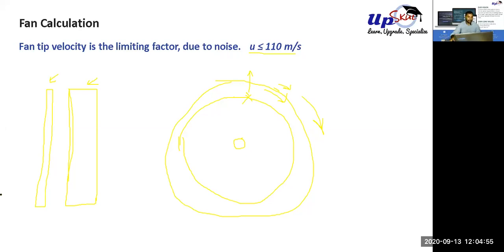For the thin profile, the fan will rotate faster and deliver the same amount of air, but it will make more noise. It will require a smaller motor, due to the lower torque requirement. So ideally what we want is a thick profile fan with the largest diameter possible.